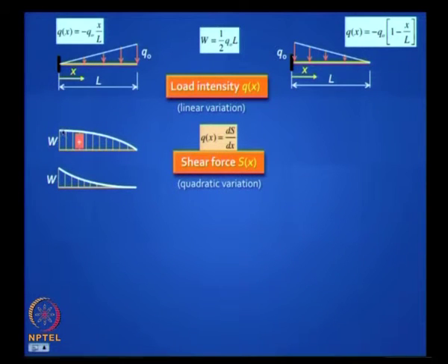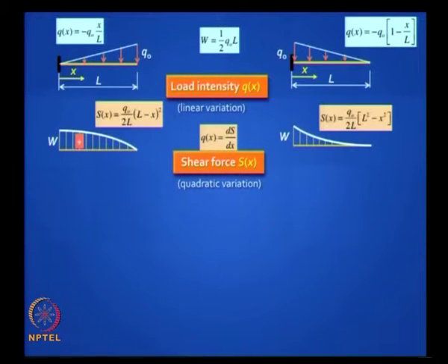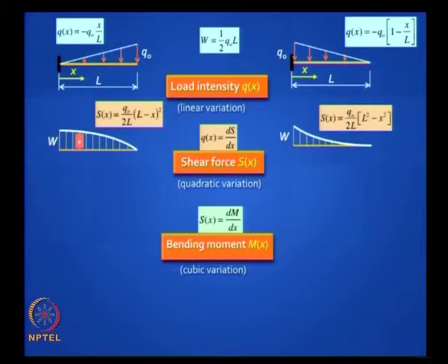Right. So you will find that the slope of the shear force diagram, here the slope is 0, it is tangential, here must be the load intensity which is 0, whereas in the lower case there is a definite slope. So actually this diagram belongs there for the other beam. So you can see where the slope is 0, there the load intensity is 0, and where the slope is maximum, there actually the load intensity is maximum. So it's a very easy way of understanding the relationship, and you can write equations if you wish.